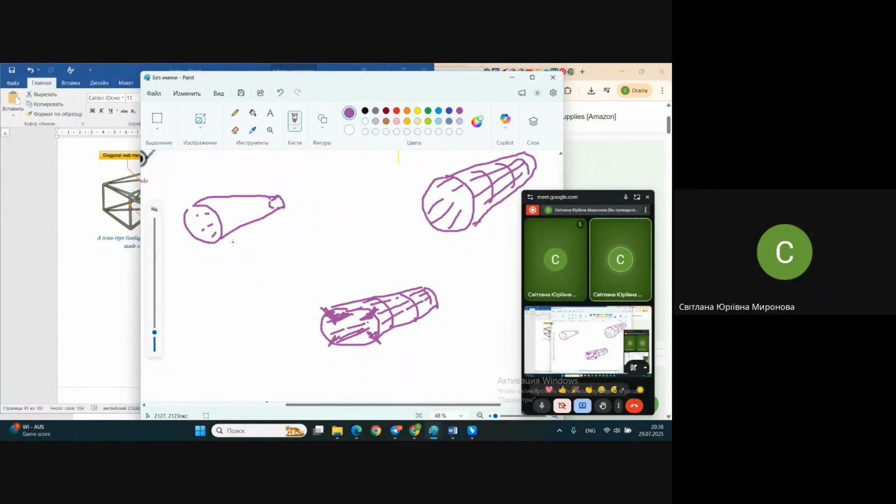In case you have the front fuselage cowling, or somewhere at the end the aft fuselage cowling, something like a cap at the end of the airplane, it's feasible to use this monocoque structure. In case it's a regular place inside the fuselage, passenger cabin, cargo cabin, it's more convenient to use semi-monocoque structure.